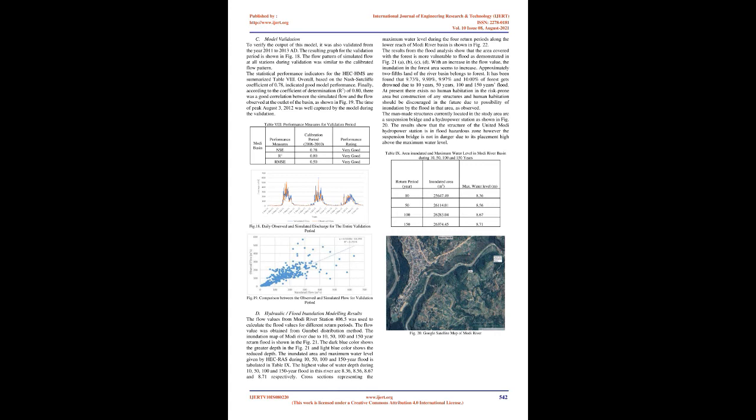Model calibration. The calibration of the HEC-HMS model was carried out based on the observed flow data of the Modi River Basin Hydrological Station, Station No 406.5, from 2006 to 2010. Fig 16 compares observed flow to simulated flow for the calibrated years, 2006 to 2010. The blue line represents the total simulated outflow and the orange line represents the observed outflow measured at the gauging station. The Nash-Sutcliffe coefficient of efficiency, NSE, was found to be 0.78 as summarized in Table 7.